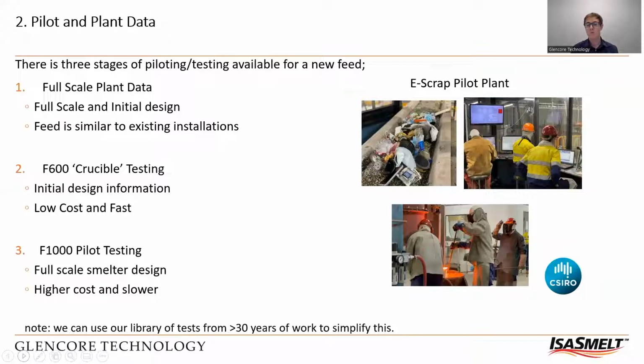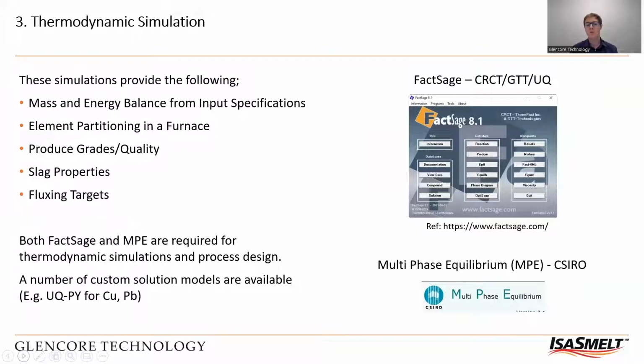With all these steps, there's sometimes information missing, and we have to fill that with thermodynamic information. Thermodynamic simulations are predictive tools. You specify all the feed materials and some general running parameters, and it will predict what will come out of the furnace. These thermodynamic simulations are really good before you've done those pilot tests, at the very initial stages of a project. These calculations are very low cost, cheap, and fast, really easy to do. But there's lots of kinetic information which is not necessarily captured.